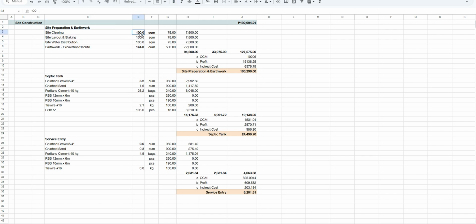It's based on the area, for example, and the cubic meter to be excavated, and I have the costing. Right here below each work, I already add the percentage for overhead, contingency, and miscellaneous, the supervision and profit, and then indirect costs like deliveries, or let's say some food and water, so that, for example, if these costs become subcontracted to another person, then it will not affect the total.